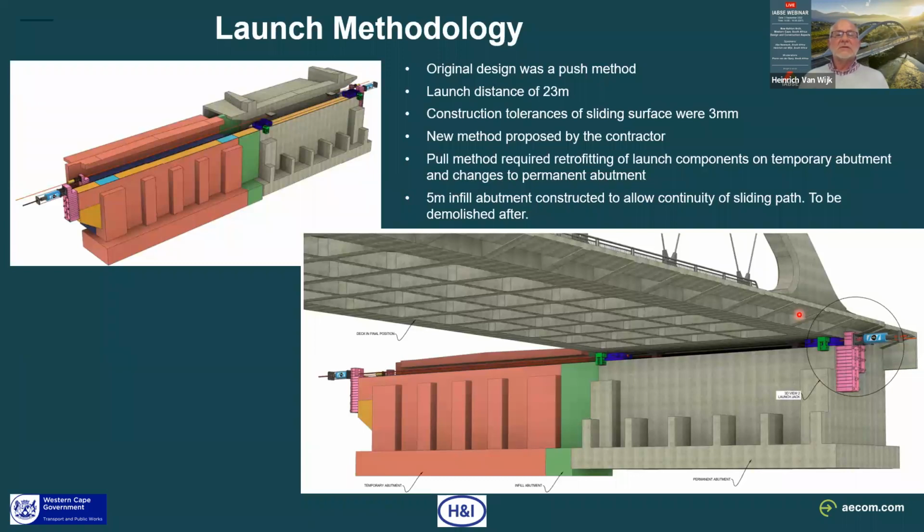On the launch, this was part of the contractor's responsibility, and they involved Naledi Engineering, a specialist in this type of exercise, to design the system. Our original requirement was that a push system was required because of concerns that with a single pull system, once the deck starts moving, you won't be able to guide it properly with the extensive elongations that will occur with your tensioning cables. That problem was solved by providing equal jacking forces on both sides, so that your bridge is launched in a controlled fashion.